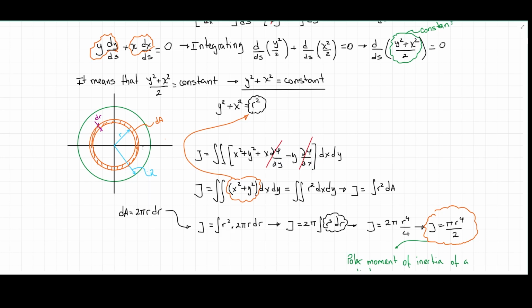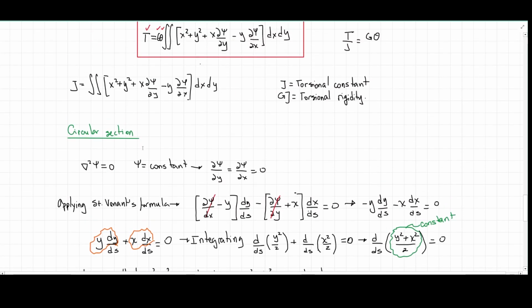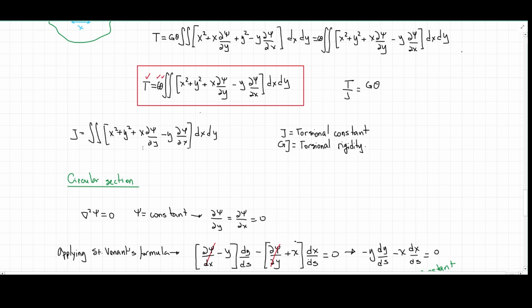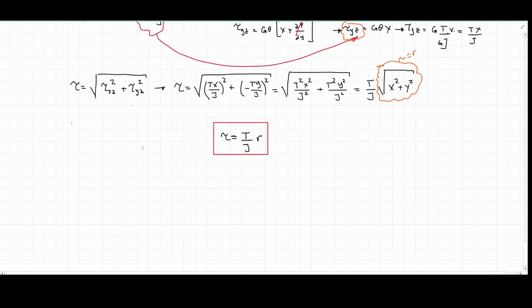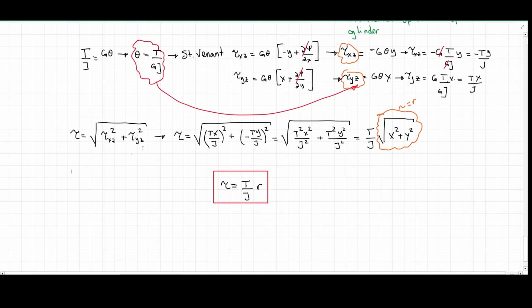And one thing that plays an extremely important role is the shear center of the piece, which is not going to be coincident with the central axis of that. Something that we will see in an exercise. But I want to close what I was going to give you today at this point by saying that this is a simplified way of seeing Saint-Venant. It could be done in a much more complex way, but so far, for what we have to do in the course, this works for us.